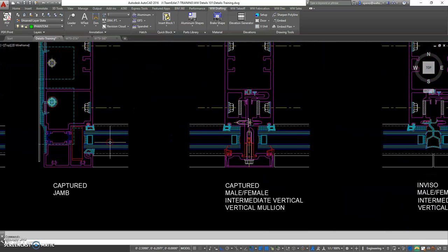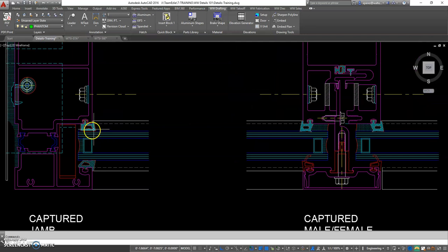Behind the glass in our verticals, these are called back gaskets. These literally are like spacer gaskets, also another term. It's creating a space from the metal to the glass. Imagine these glass pieces are getting installed laying flat on top of a table. These spacer gaskets are pretty dense, and they help hold up the glass this set distance until this sealant cures in the shop.